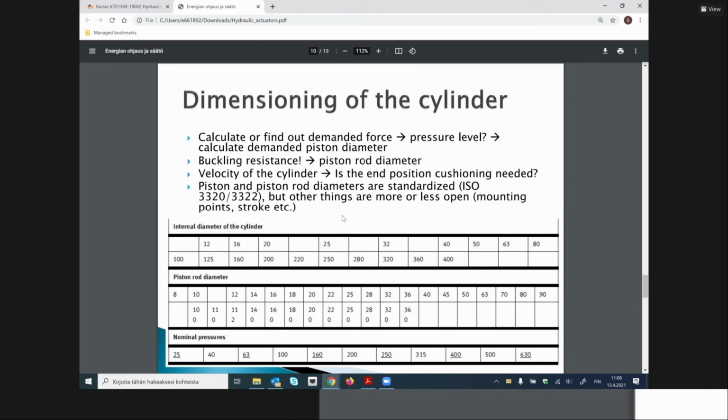In pneumatics, it is different. In pneumatics, there are standards, and if you buy, for example, a Festo pneumatic cylinder, and you need to replace it, you can very easily buy an SMC pneumatic cylinder, and it goes there without any problem. But it's not the case in hydraulics.